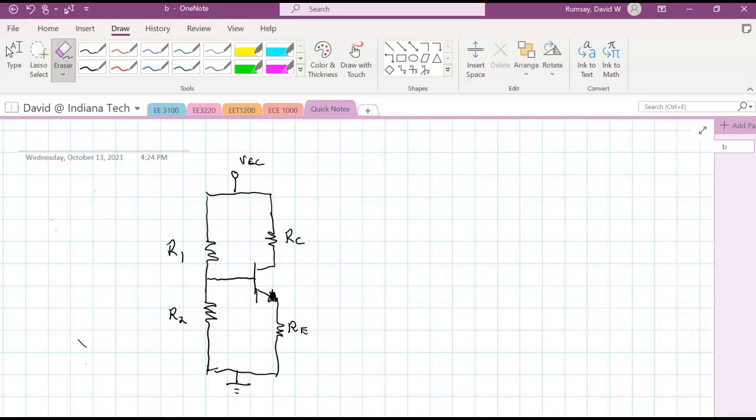As I said, this is designed as an amplifier here, and we don't really see it because all we're working on this week is doing what we call a bias stable circuit. So in order for us to even run this as an amplifier, we first have to bias the transistor in the forward active region, because that's where we can get amplification from putting in a signal. And that's what we'll look at next week, actually amplifying with this kind of circuit.